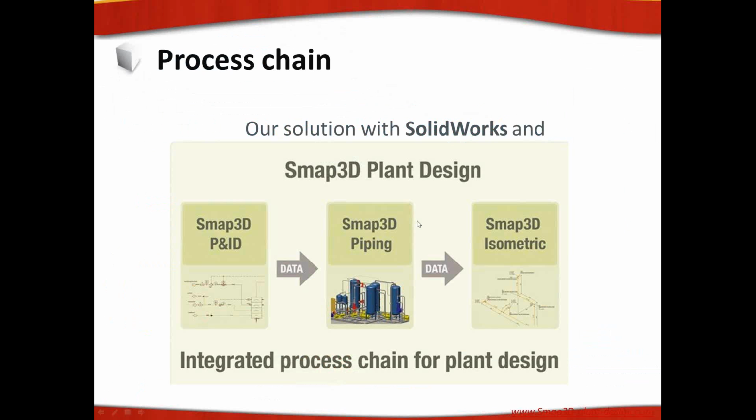So first, I want to point out Smap3D is a third-party application that is integrated as a plugin, but it also has a few standalone applications too. In particular, one of the solutions that is very intriguing for folks is the PNID capabilities. It's essentially a separate application where you can sketch, if you will, or design 2D drawings, but these drawings give you intelligent symbols and intelligent sketch geometry, pipes, and so on, where it's all driven by an integrated database. And this can be very beneficial in building bills of materials and items and so on and so forth. So it can be very, very beneficial just to have that package alone.